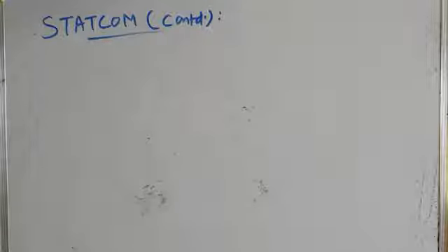In the last lecture I have discussed with you that Statcom is basically a converter based shunt compensator. It comprises a three-phase voltage source inverter, and by inverter output voltage control with the help of modulation index control, we are able to exchange reactive power with the transmission bus to which it is connected in parallel. And if the phase angle between the inverter output voltage and the bus voltage is controlled, we can also exchange active power, provided the DC bus has energy storage like a battery energy storage system.